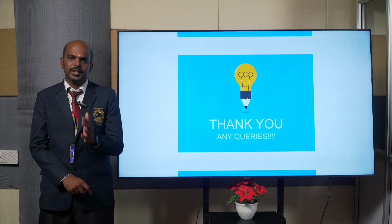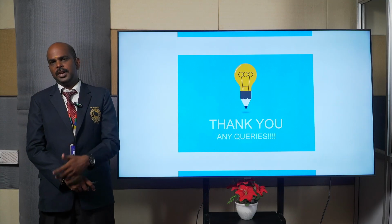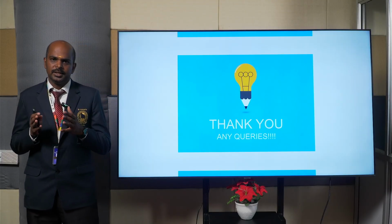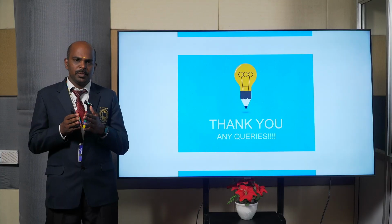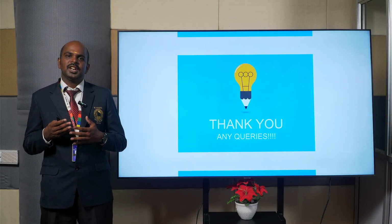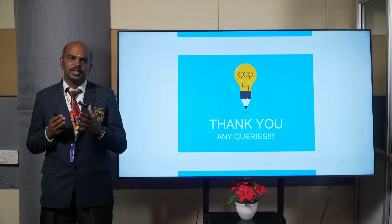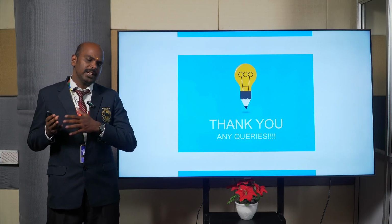For all the electronic devices, the operation is almost based on forward bias and reverse bias. At the junction, the depletion region disappears at one stage, so current flows in forward bias. At another stage the depletion region becomes wide, which is reverse bias. Based on this, and on the minority and majority charge carriers, we have two types of breakdown also. One is Zener breakdown, another one is avalanche breakdown.